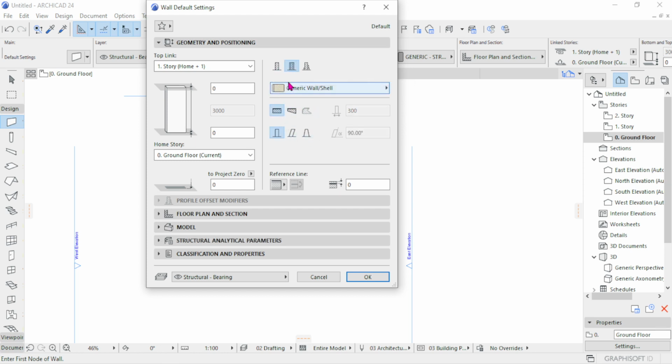And remember, currently I'm at composite. At composite, there is a polygonal type of a wall that is currently off. But if I choose structure here, or I choose the basic structure, you can see now the polygonal type of a wall is there. And of course now, you define the various measurements in the drawing area graphically. So it is important that you note that we have the three types of walls.